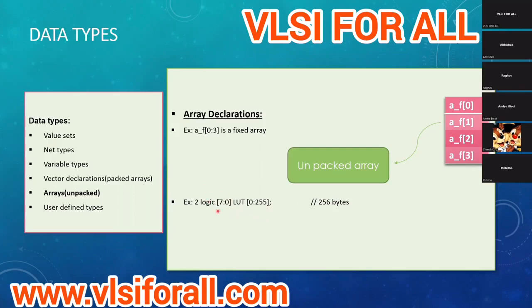And on the unpacked side, the 8 bits, you can even slice it. You can use like 7 down to 3 also. If you want to access only 4 bits, you can consider this as 8 wires coming from any logic, and now you can use all the 8 wires together, or you can use 4 wires together, or any single wire from these 8 bits.